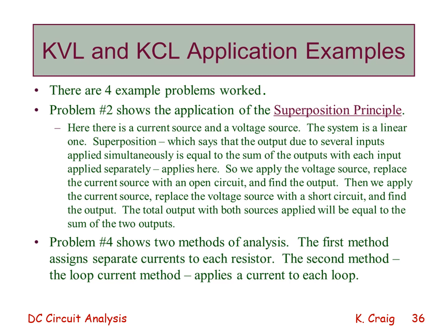In this problem, there is a current source and a voltage source. The system is a linear one, so superposition applies. Superposition says that the output due to several inputs applied simultaneously is equal to the sum of the outputs with each input applied separately.